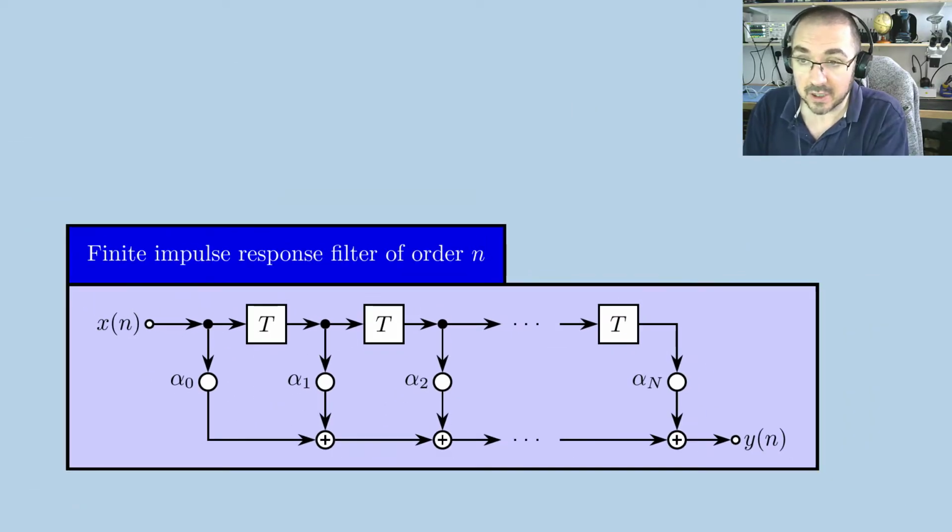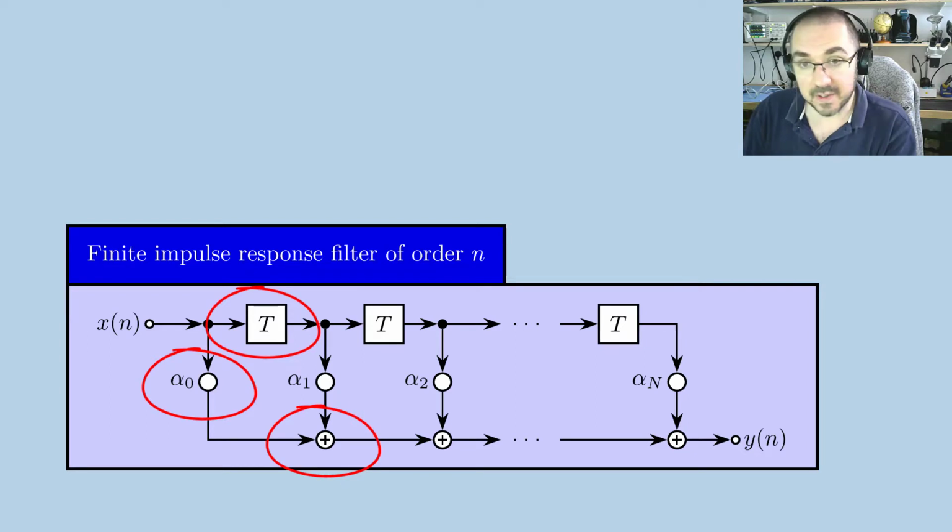Now, we all know you can make analog filters out of inductors, capacitors, and resistors, but digital filters, you can actually make them out of three main things too. So you need your delay element, your multipliers, and your adders. And if you combine these in the right way, you can make a digital filter with an arbitrary cutoff, roll off, and all the same kinds of properties that you get with analog filters.